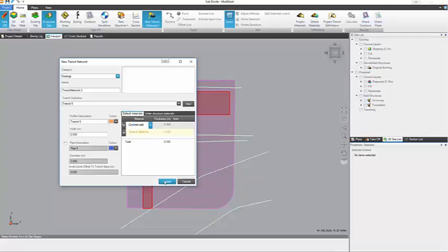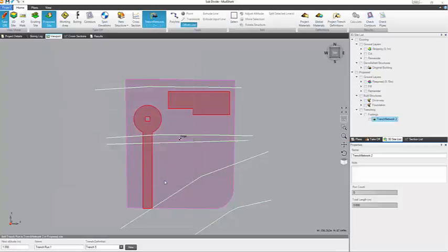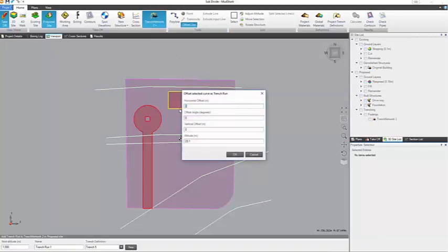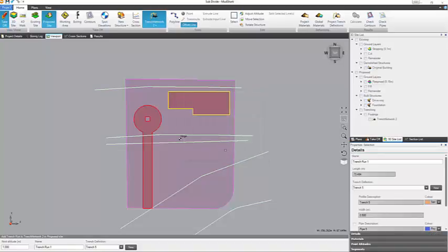Concrete slab and create. Now what we want to do is do it as an offset line. Normally the default is to trace it with a polyline, but we're going to go offset line from the boundary of our building, and we know we want to be half the width in, so that's minus 0.25, and we want it to be a meter below the surface of the building slab, and the building slab's got 300 mil of materials in it, so I know I need to go 1 minus 1.3 down, and I'll go OK.